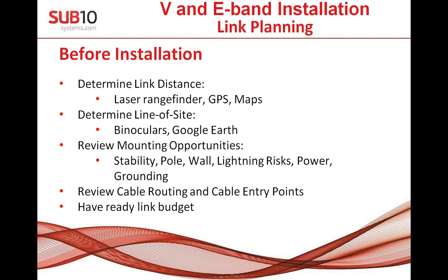It's really important to check the grounding, because in some buildings you can see a big difference between the ground on the roof and the ground used by the electricity. Just be sure that your mast is grounded. It will minimize the risk that the link is, for example, rebooting or not working as you expect because of a big fluctuation in the power level.